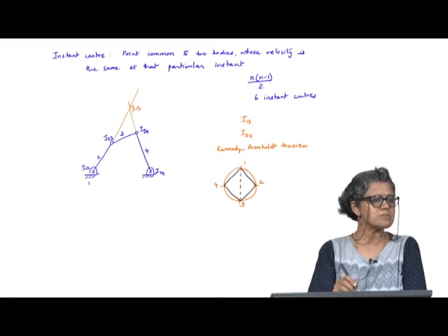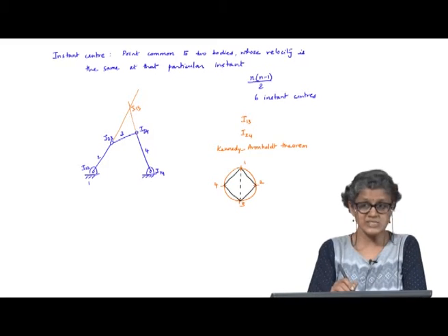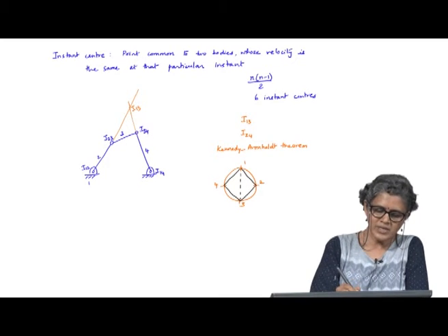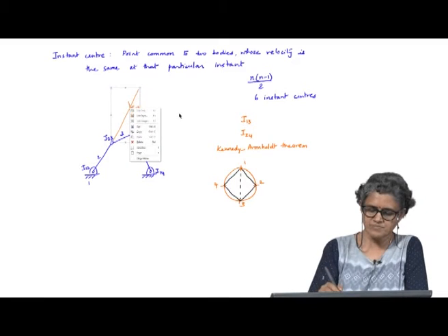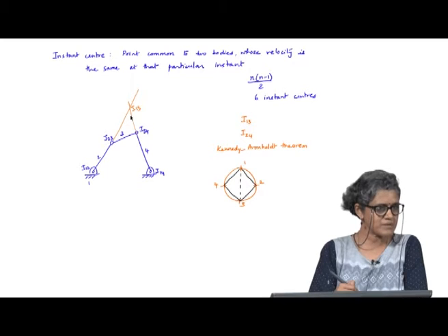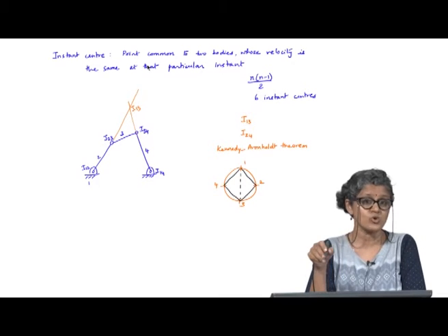We have seen I13 before when we looked at centroids, fixed and moving. So, I13 is special because it belongs to body 1 as well, which means from the definition of the instant center, its velocity is always 0.